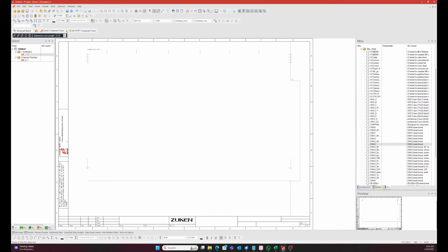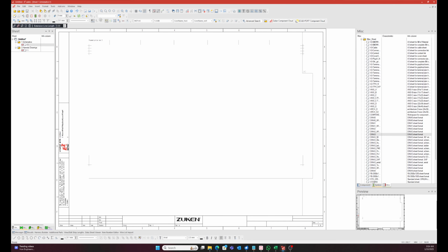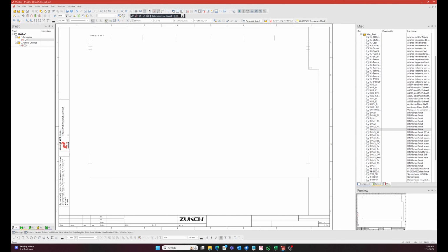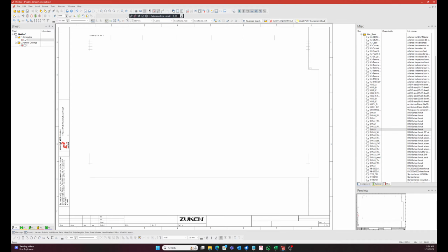So the next is the top workspace. You can see it's a bit of a mess. Like I said, I've got a pretty high resolution on the screen, so I've got plenty of space. But if you're using a small portable laptop, then it can get a bit tricky. Move these across whichever way you want. It depends how you're using E3, and a lot of things for that matter. But in my case, I don't use pneumatics too much. So this is the hose tube settings. I can right click and remove hose tube settings. If I don't use it, then there's no point.